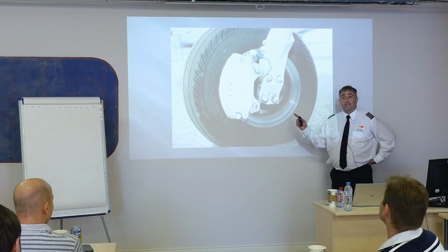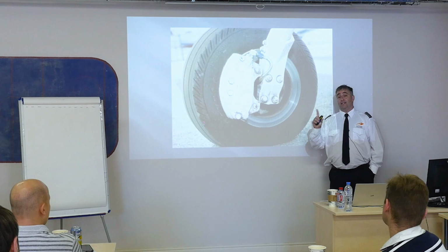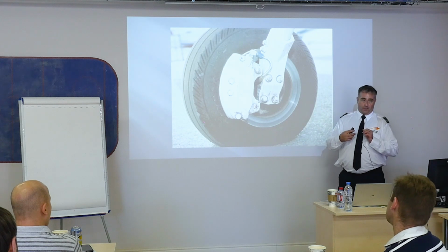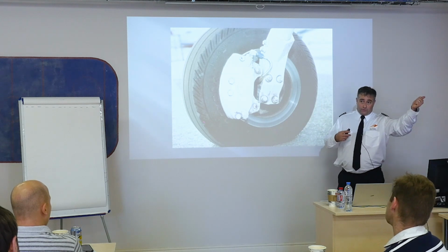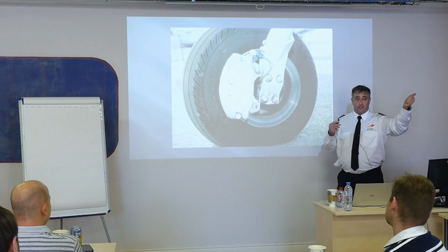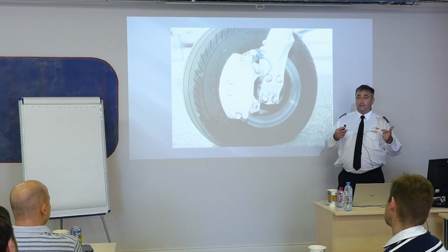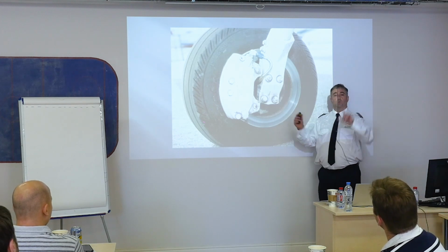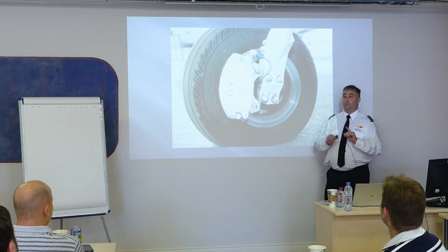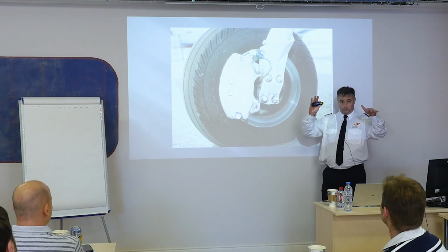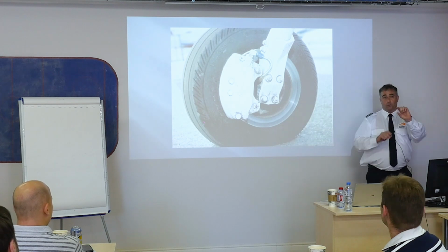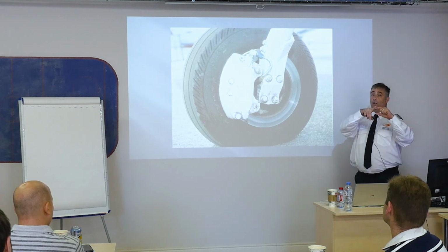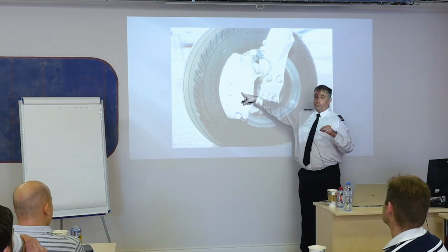Now, this is a hydraulic system, and almost every airplane will have one. Hydraulic systems typically run a wide arrangement of different things. Retractable landing gear, they'll have that as a hydraulic system. Flight controls, you'll have that as a hydraulic system. You'll have all sorts of different hydraulic systems depending on the airplane that you're flying. This airplane has one hydraulic system, and it's a very simple one. There's a master cylinder behind each pedal. Each pedal on each side has its own master cylinder, which is just a way of transmitting hydraulic pressure from your toe through this line to the brake caliper.